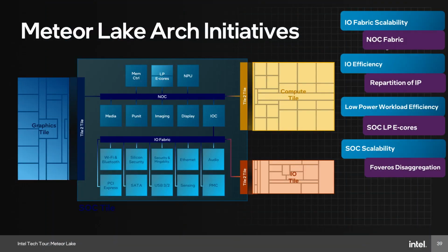In Tiger Lake architecture, think about this like we have one highway. That highway was getting shared with IPU and the VPU and the display. So if there is a jam, then some other IPs or the agent IPs actually had to wait. In our case, the way I would say this is that Meteor Lake is the true SoC that actually had multiple highways for different agents. Meaning that, for example, if IPU wants to talk to the memory, you don't necessarily have to wait for the others. You actually have your own channel and go to the memory. If you have display, which needs a higher prioritization, it will go to its memory link directly.